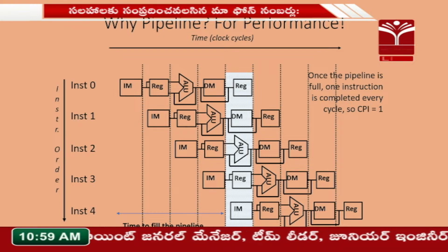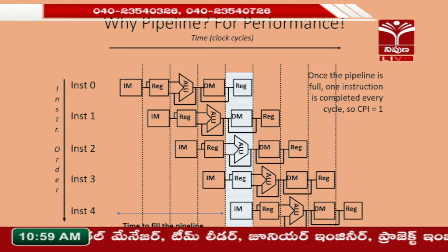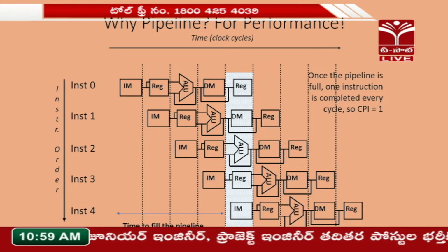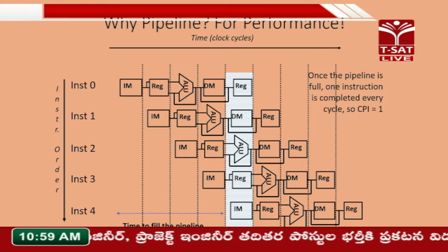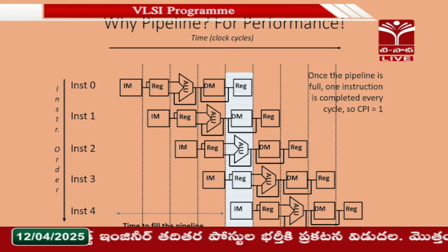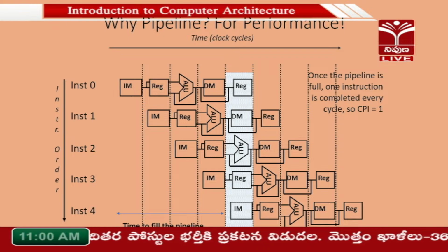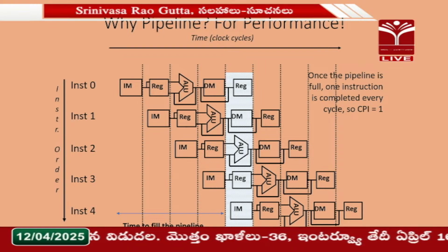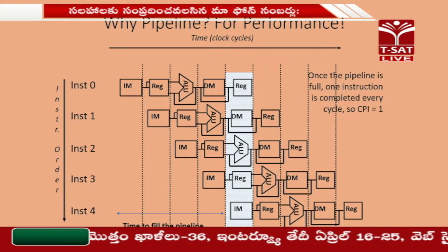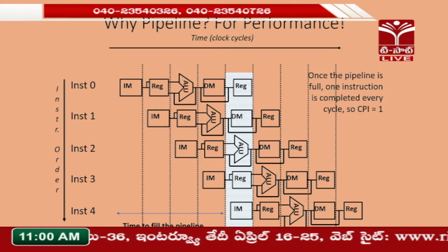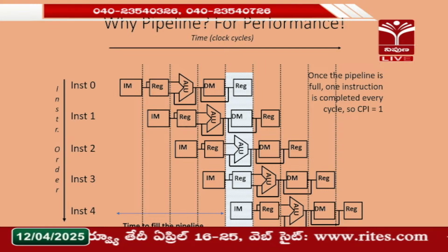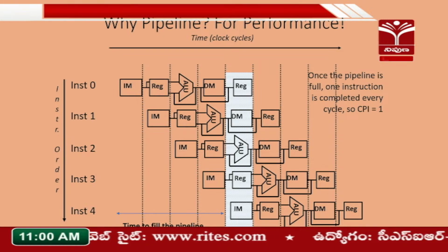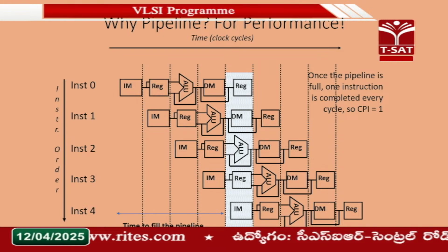When I say the complete pipeline is full, every resource is busy, because each stage is a resource, like the 5 resources and 5 stages shown before. If everything is flowing normally without any hazards, after instruction 4 all the units are busy and you are executing one instruction per clock cycle. If you interpolate this to instruction 5, the next cycle also will be fully occupied.